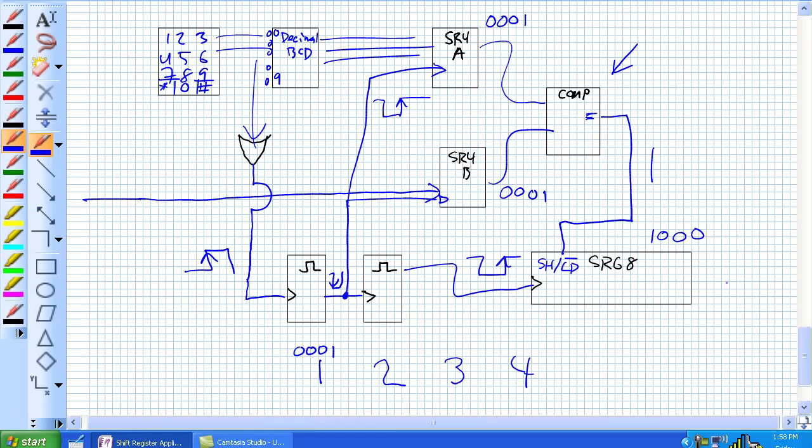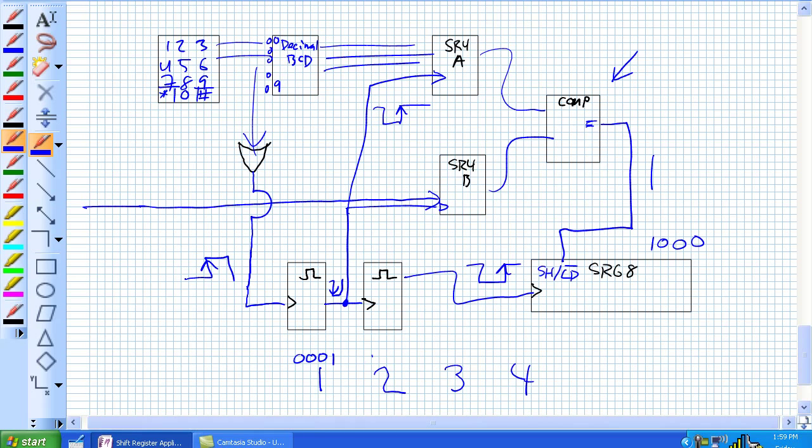So now it goes on and loads a 2. And you just so happen to press 2. And again, it says wake up. It enables our 2 shift registers through that one shot. It's basically saying load 2 in. You got 2 there. Comparing them, again, 1. This one shot has produced a clock signal right here. And as that clock signal goes from low to high, we've got a 1 on our shift command, and it shifts 1 over. We're almost there.